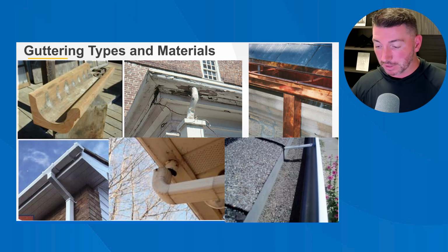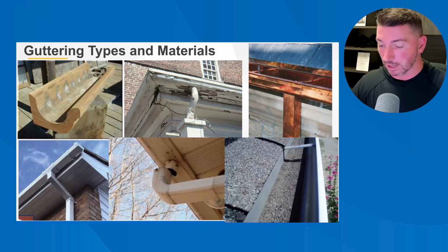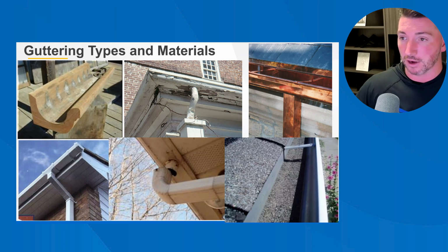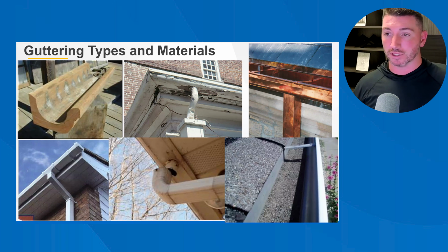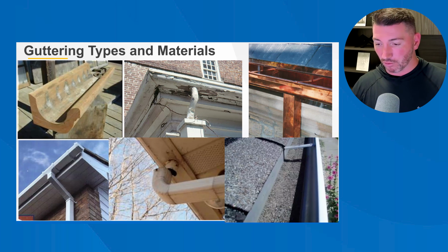Are the gutters blocked by any debris or even rooted vegetation? I can't tell you how many times I've walked up and seen little trees growing in the gutters. That's deferred maintenance, and that's something that I'd want to call out, because that is going to stop water from flowing freely into the gutters, and usually it backs up, runs over the back before it runs over the front in some instances, because you've got shingles there and underlayment that will kind of wick that water up and rot out the decking right at that edge. So take a good look at the bottom of the gutters.